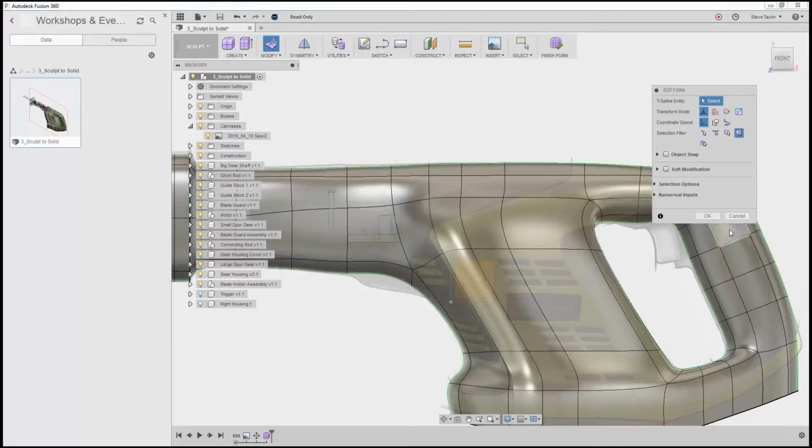And when you're doing these modifications, don't try and do every single edge one after the other. Just jump from one edge to the next, leave a couple between, and let Fusion do the smoothing over between the two as you're going along. A lot of it's practice, but also paying attention to what happens. So as you're doing it, see what happens, and then modify your approach depending on the results that you want.